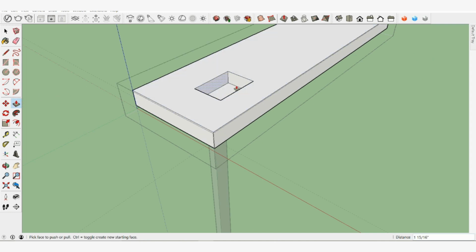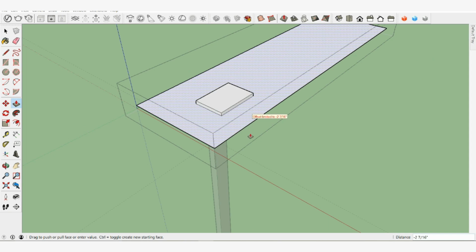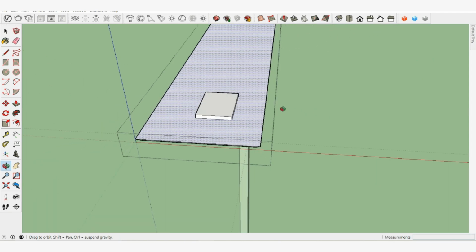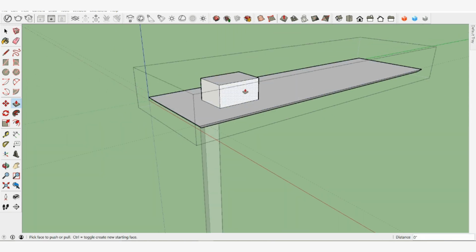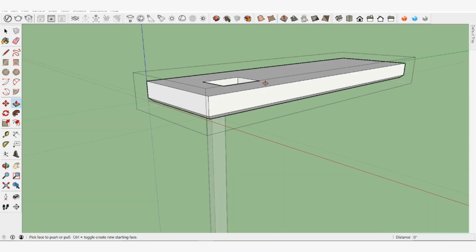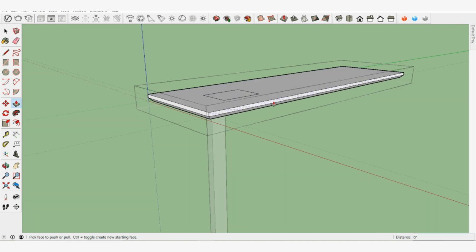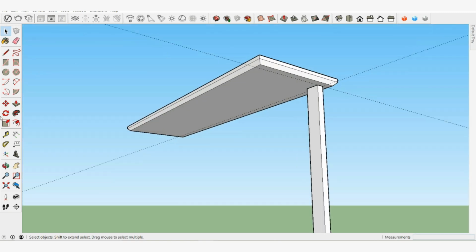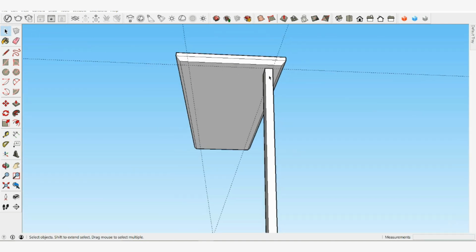While you are editing a group or component, you can draw and divide surfaces and edges. Use push-pull and other tools. But once you close the group, anything you draw is outside of the group, so it's important to know when you are editing or working outside of a group or a component. With that understanding, if you did modify your group in any way, undo any changes back to our original tabletop and leg, and let's copy the leg to the back side.